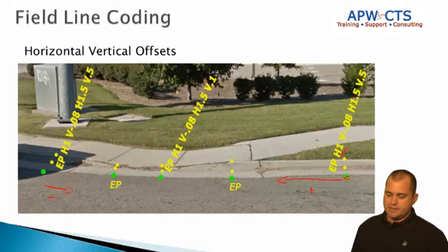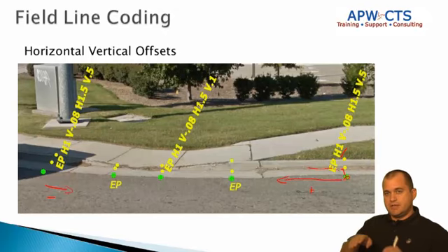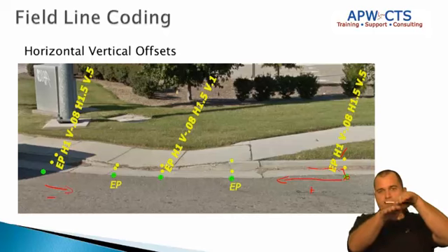Okay, so here I'm going -1, and that's a 1 foot offset. It's going to draw that offset over to that point, which is going to pick up my gutter pan or my flow line. And then I'm doing a V -0.08, so it's dropping 0.08 to give me the vertical relief. So my line basically gives me my gutter pan.